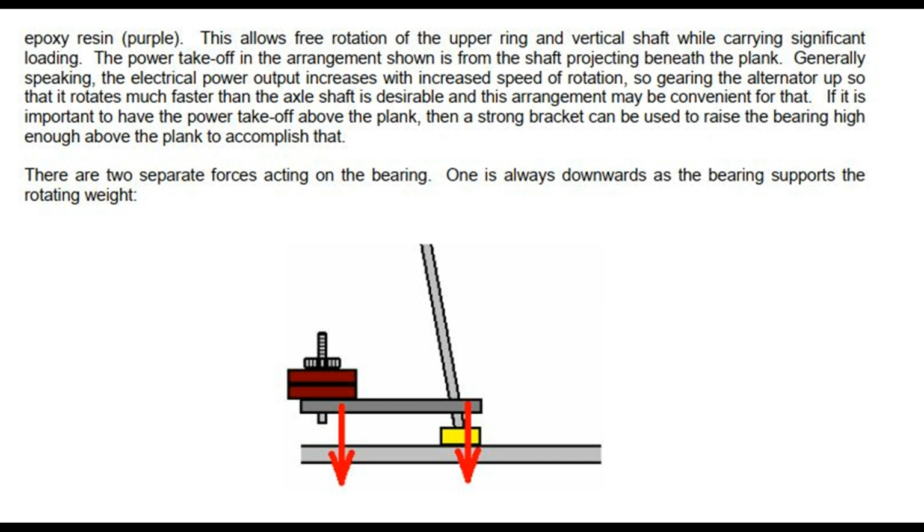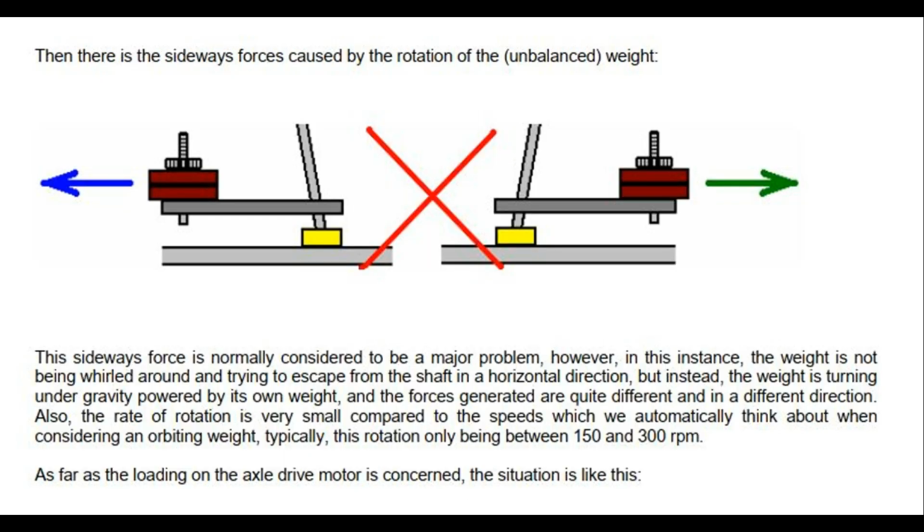There are two separate forces acting on the bearing. One is always downwards as the bearing supports the rotating weight. Then there are the sideways forces caused by the rotation of the unbalanced weight. This sideways force is normally considered to be a major problem.